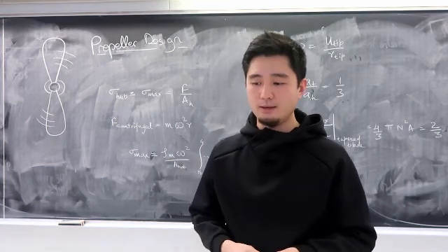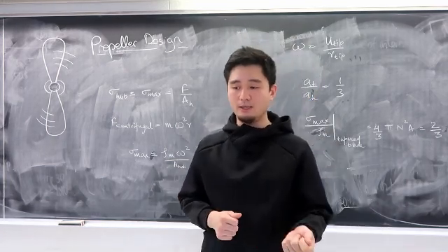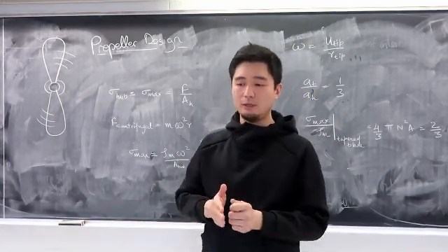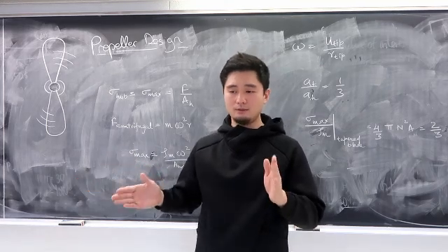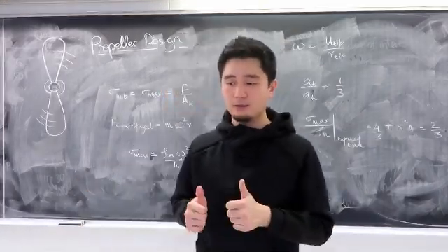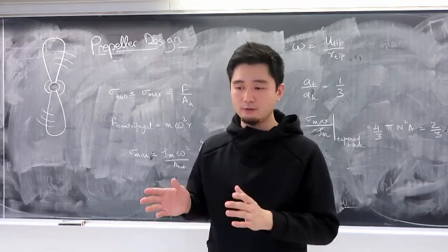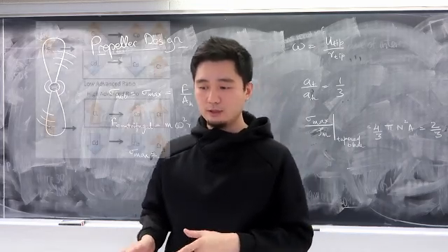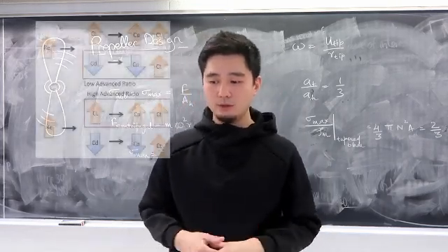So the comparison between the center hub and, let's say, 80% of the propeller length outwards, the difference is actually quite significant. So in higher Reynolds number, this implies that there's low drag coefficient and higher lift coefficient.